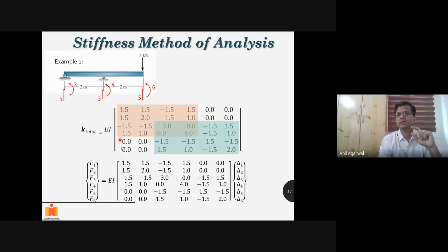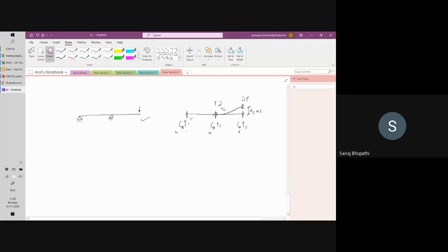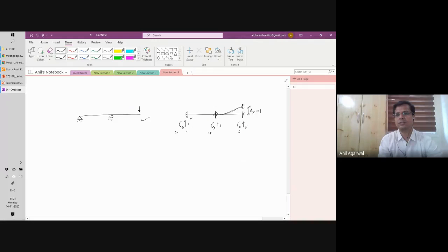That is what the stiffness matrix means. So this entire column here corresponds to delta 5. And any term here ensures that no other deltas are present, if I'm talking about only this one. Is that clear? Does that make sense now? Yes, sir. So if we maintain these restraints at 3 and 4 location, then of course there is no additional force required at 1 and 2, no matter what I do at 5 or 6 for that matter.